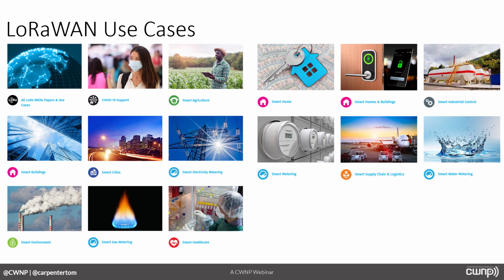And when you can answer those 3 questions, the data rate, the power, whether that's battery life or power consumption, and the range, you'll know whether something like LoRaWAN or something like Zigbee or Bluetooth or wireless HART or something else is the better solution. So the key thing is to understand what the protocol offers and then determine your needs from there.